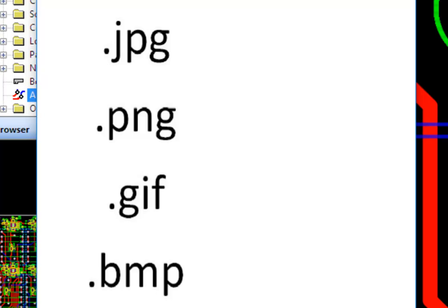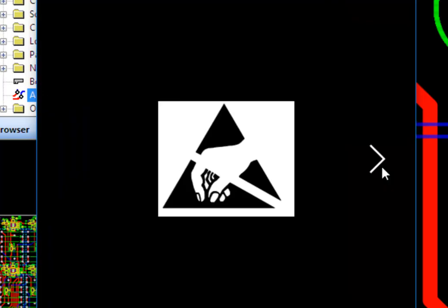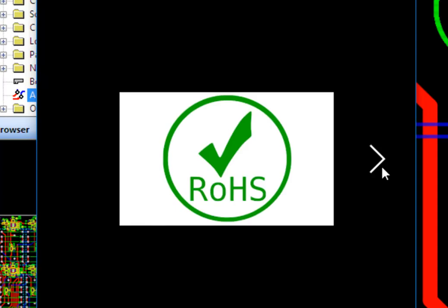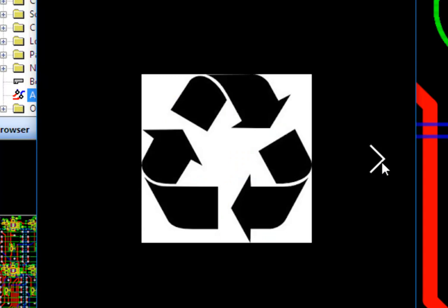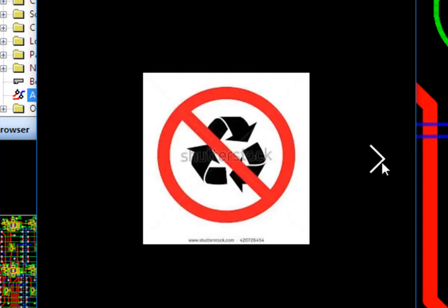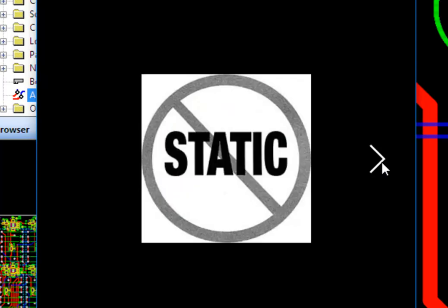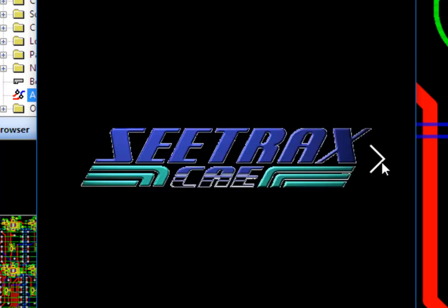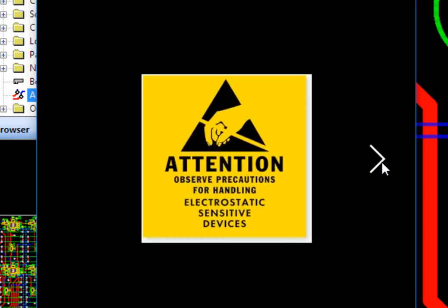copper layers. Because the images will be rendered as either silkscreen or copper, there are no grayscales in the resultant image. So try to use clear, sharp, single colour images, as they will transfer most effectively. Bear in mind, the coloured images, even those grayscale images, will result in a single colour, so something like the C-Trax logo isn't going to transfer too well, nor will small images with lots of detail.